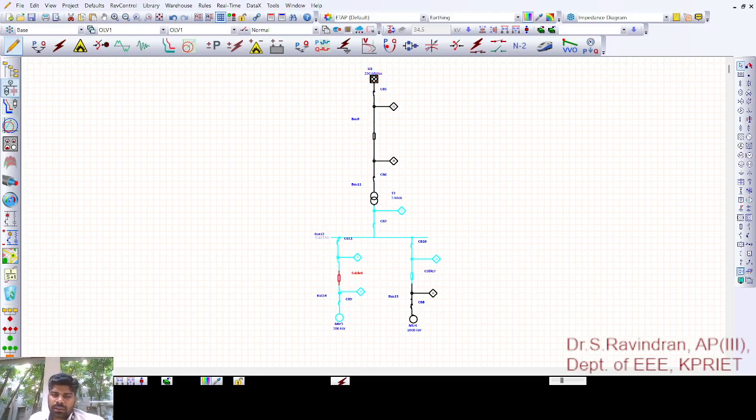So if this is the case, a cable is in the system, so we are responsible for protecting the system separately. If a fault happens in the motor, the cable should not get damaged, so I will cut off the fault over here. If a fault happens at the motor cable, my bus or other system should not get damaged, so I will cut off over here. If a fault happens at my bus, my transformer should not be faulted, so the trip happens over here. If the fault happens beyond the transformer, this circuit breaker will open. If it happens in this transmission line, this will open.